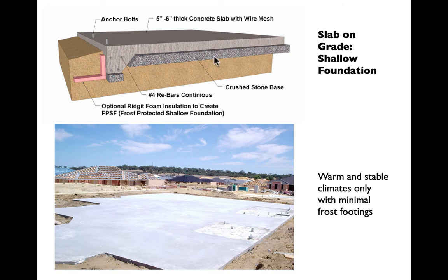But also because it's porous, again, it's going to keep water away from just under the slab. And even if we're heating the slab, we may be a little bit concerned down the road if there's a long power outage or if the building is without heat for a while. We don't want any water there that's going to freeze and try to push up on the slab.